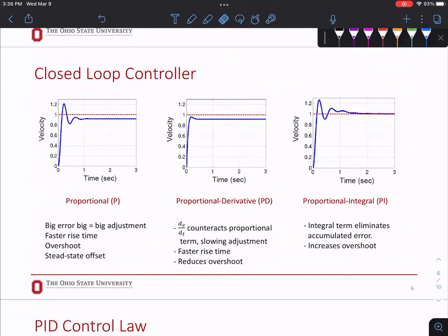So if we only add proportional control, if you had a transfer function, you will see that it compensates. Like if you had a big error, the first thing you do, you just add P. It just means your system doesn't have enough juice. Just give it some gain value and bring everything up. It would bring your error to a smaller value. The other impact is it makes it faster. So faster rise time, though that doesn't say anything about settling time.